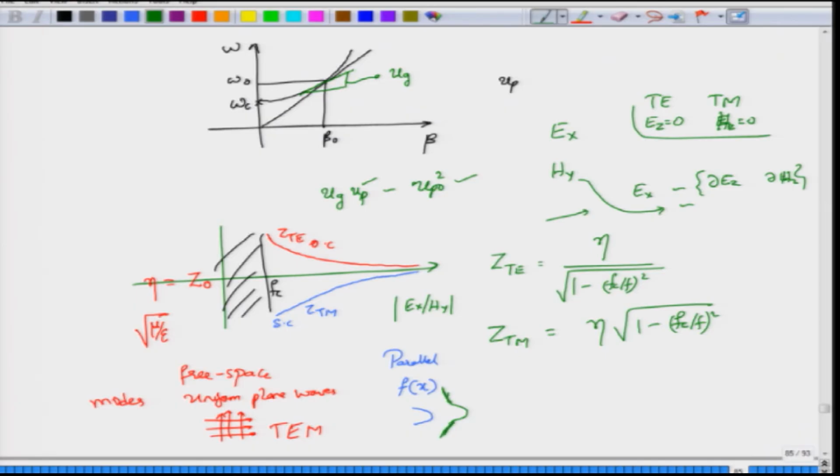So, this was for the dielectric waveguide and this was for the metallic waveguide. And when you go to a fiber, that would correspond to a cylindrical rod. Again, for the metallic waveguide we have not really shown what the solutions are, but you can guess the solutions to be some sort of Bessel functions.